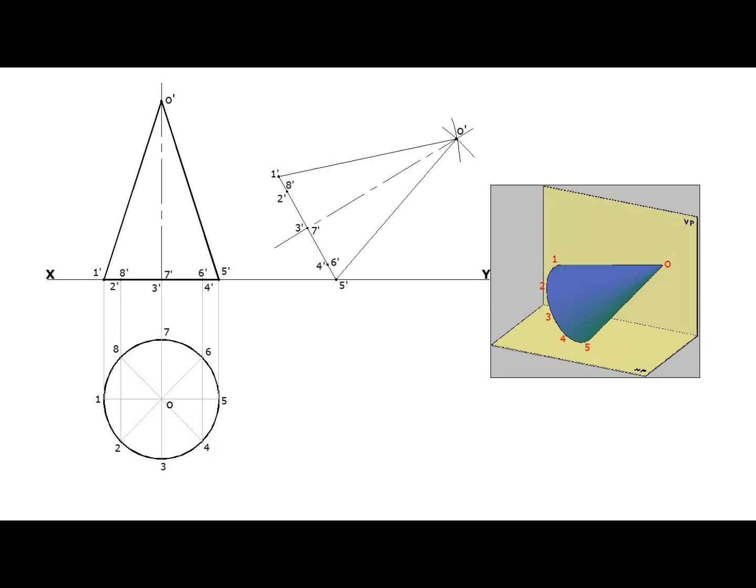To draw the second stage plan, or final plan, project all the points from the base and apex point. Project all the points of the first stage plan, horizontally. Mark the corresponding points of intersection.